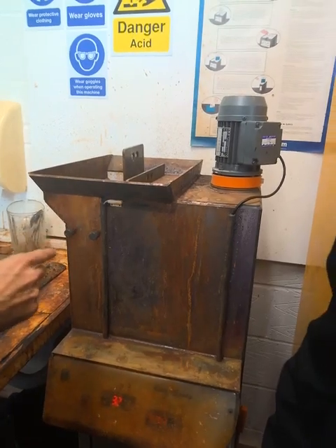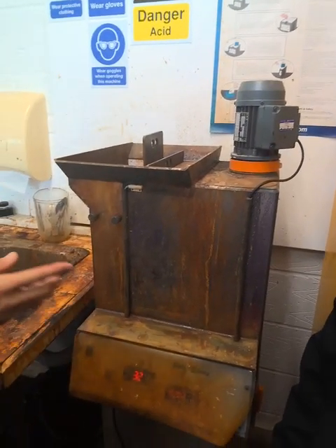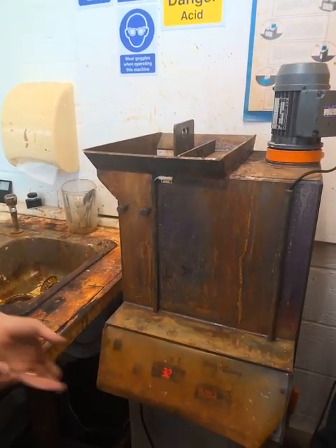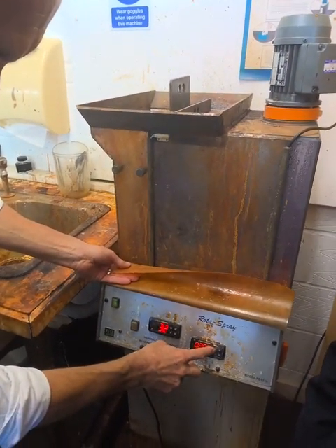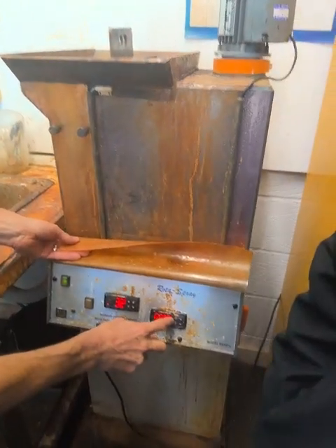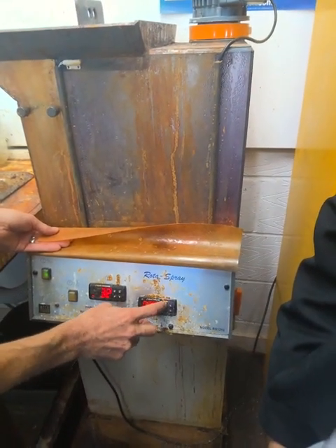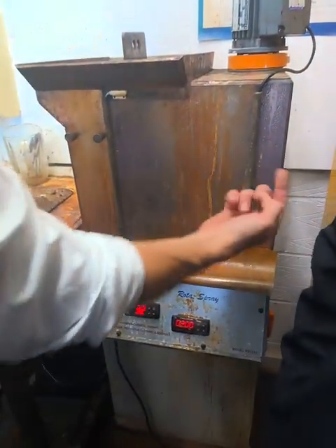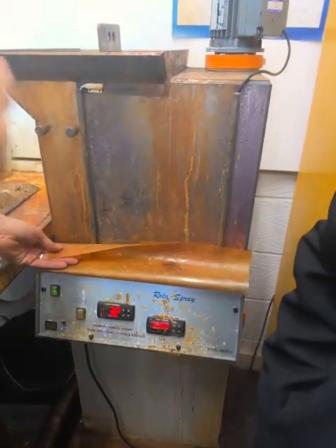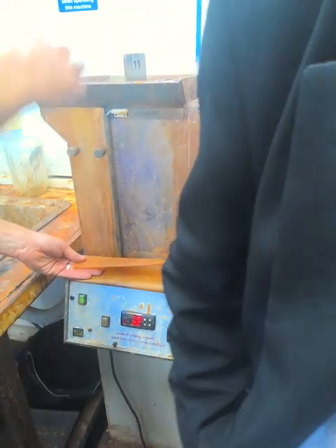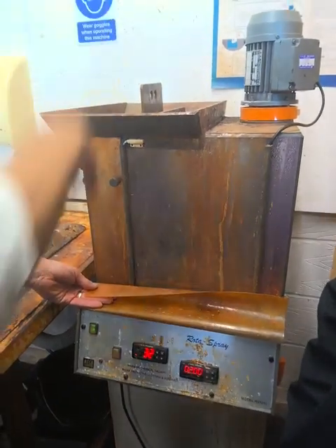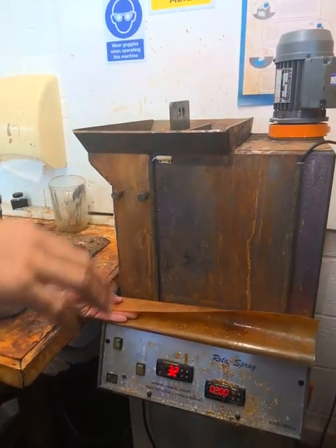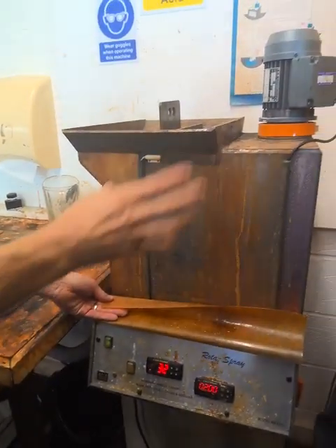I put it in the machine, and what I would do now is I'd turn it on for about 2 minutes, alright? I press this button which says U. I turn that on, and the motor spins a propeller, and that projects lots of acid onto that PCB. As it goes, that hot acid then washes down and it takes away the copper. It's what's called a jet acid etching machine.